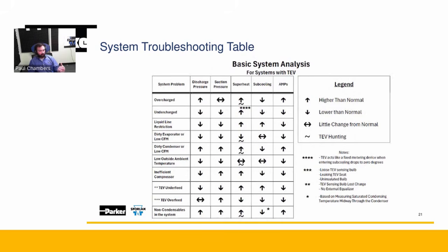But go through this line by line. Do you understand why it is doing this? Draw out your system next to it on a piece of paper and say, why is my amperage higher on this? Is it doing more work? Is it not able to reject heat? Are you asking the same of the system? These are the basics of refrigeration, that if you can understand why a system would have these reactions, what the 4 components do, you will be a much better troubleshooter, much better all around engineer anywhere in this industry.